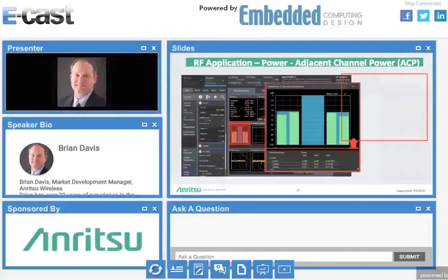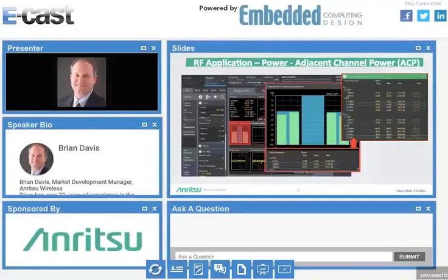Adjacent channel power. This is also a very common measurement. It's the power contained in a specified frequency channel bandwidth relative to total carrier power. So you want to maintain the call quality by avoiding channel interference. So you want to measure and reduce this amount of adjacent channel power that could be leaking from the transmitter on a mobile phone.